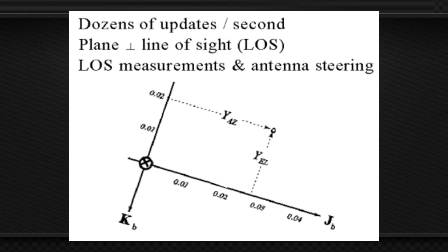We don't need trig because in order to track using a narrow beam antenna, those projections must remain always within that narrow cone. So as long as we know the direction of those crosshairs JB and KB, we are able to calculate the instantaneous interceptor to target vector in 3 dimensions.